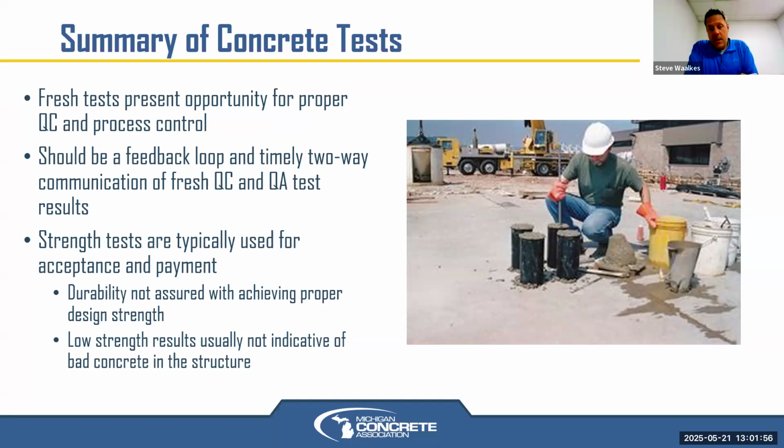The strength tests are typically what we use for acceptance and payment in concrete, but that does not mean we'll always get durability, because we just got strength. It doesn't always come along with it. But also the converse: low strength does not mean that we have bad concrete necessarily. It just means we need to look at why we might have low strength test results.